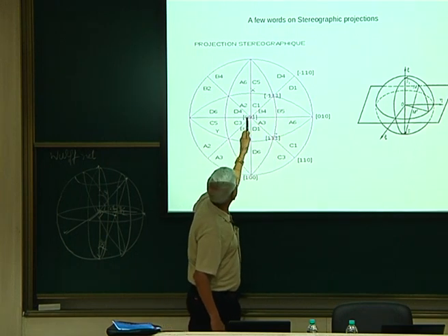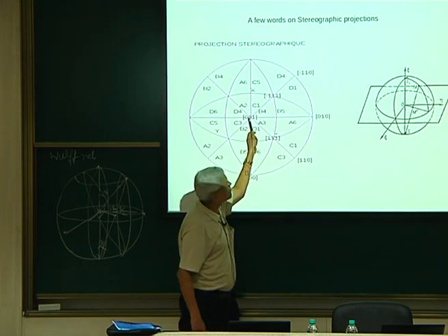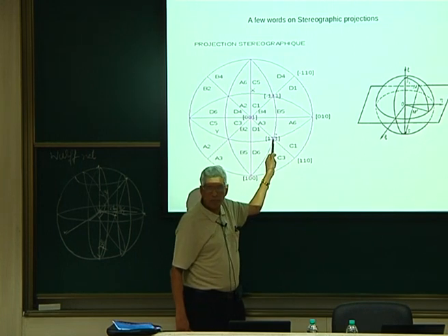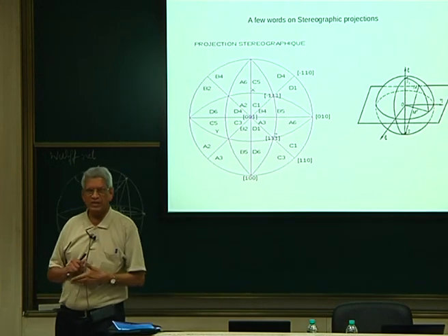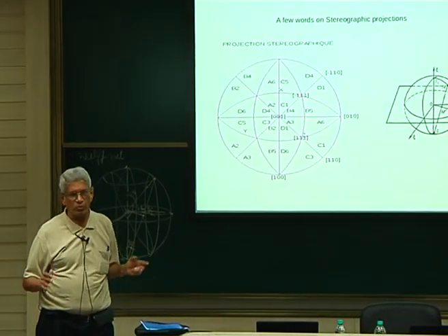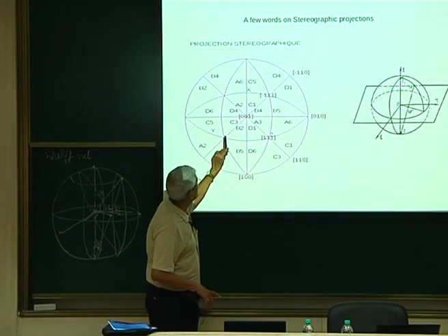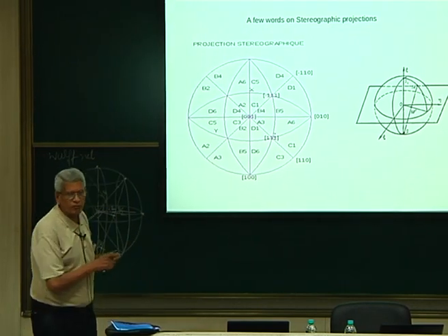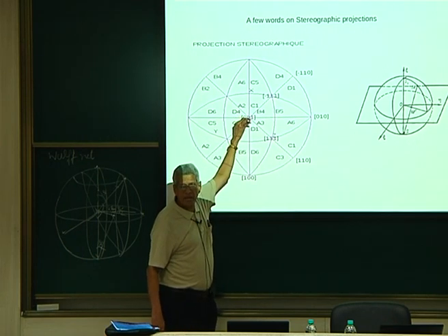But these two, if we look at it, make an angle of essentially 45 degrees with respect to the beam orientation, and the slip plane makes an angle of 54 degrees. So both of them have the possibility to operate. So with respect to the 0 0 1 orientation, for every slip plane, there are two slip systems which can operate. That is why for this orientation, we will have 8 slip systems which will be active, which are equally probable.